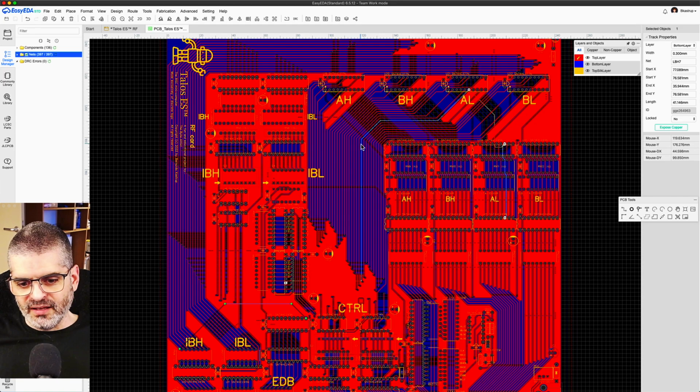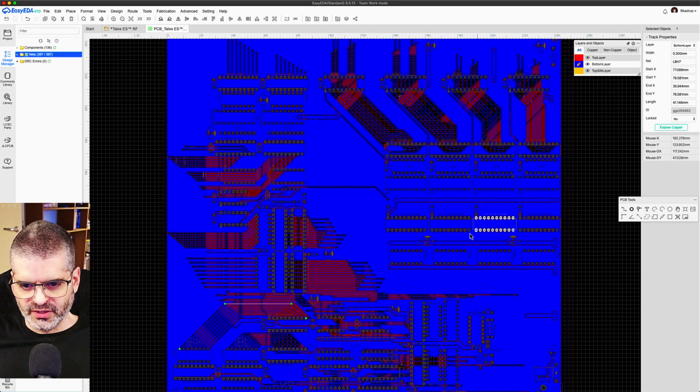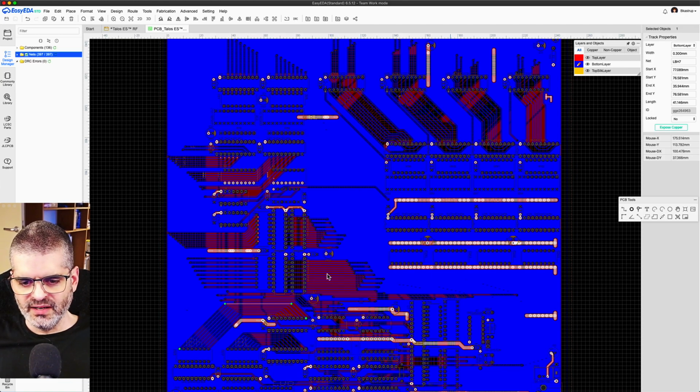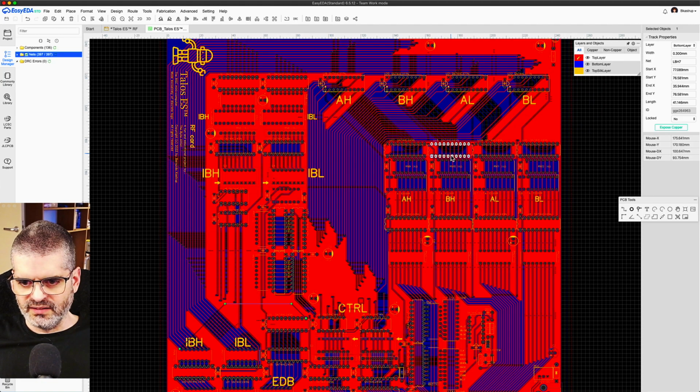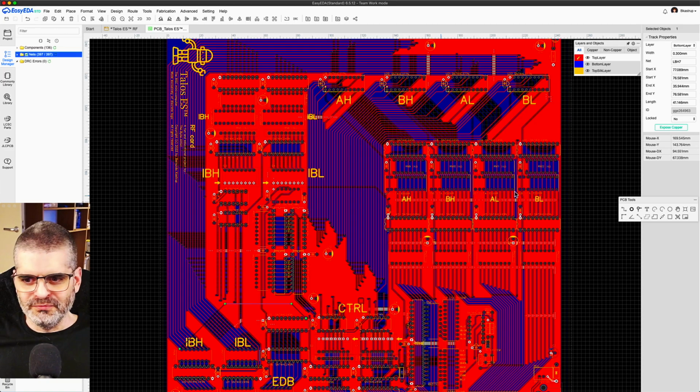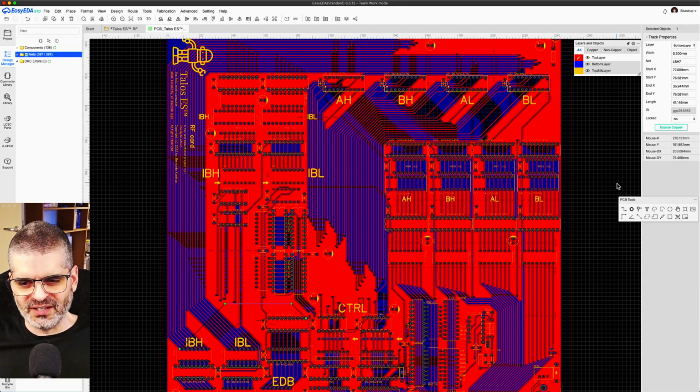And I did this on purpose because I could have connected these buffers here to the bus via horizontal lines. Let me show explicitly. I could have stretched these horizontal lines here further and connected the buffer to them here, instead of connecting these buffers there going upwards, which is what I did. These buffers connect upwards. You see, they go up. Now, why did I choose this as opposed to the alternative I just discussed? Well, to make sure that as many nets as possible are snakes, as opposed to, I don't know, crabs, lines that branch out several times, because you just get a lot more reflections if you do it that way.